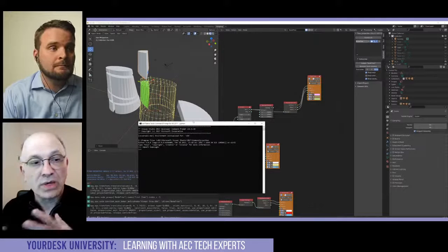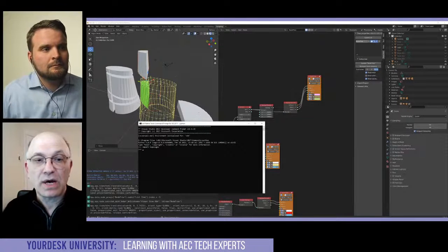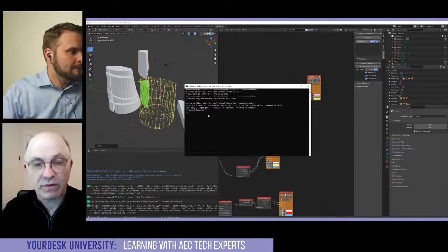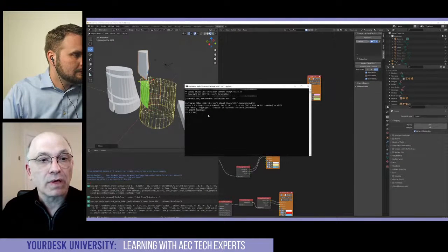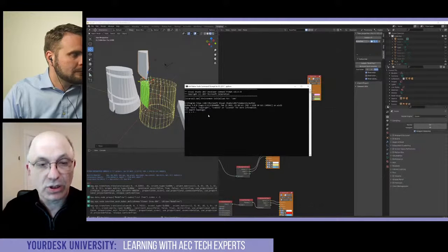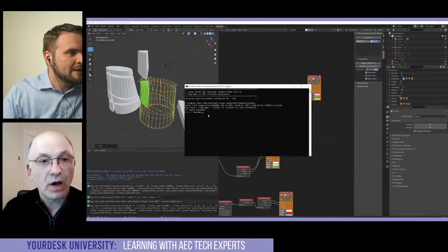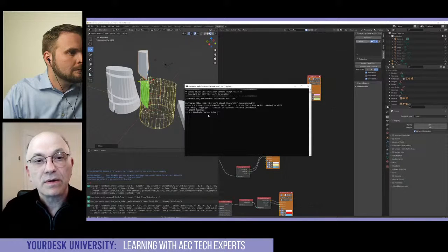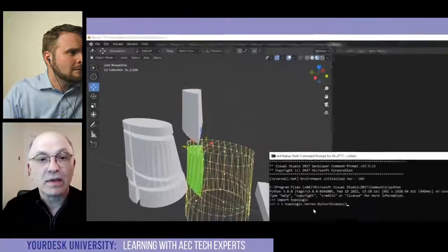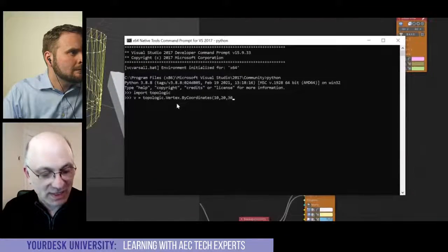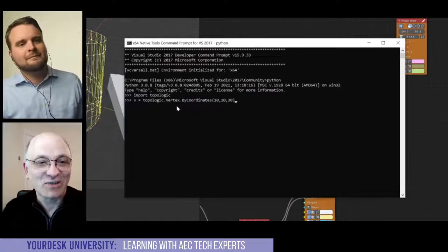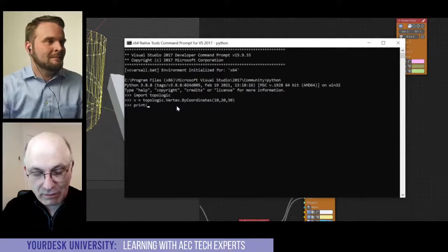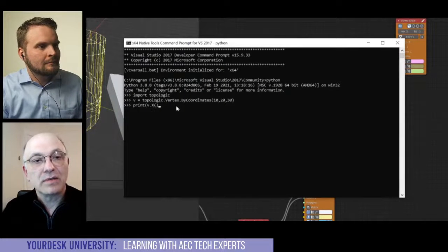In Python there is no visualization. Right now you saw I loaded it into a Python console, so I can say v equals topologic. Sorry, I have to do topologic dot Vertex dot by coordinates. Sorry, it's going to be a lot of typing, obviously. 10, 20, 30. As Theo always says, I like 10, 20, 30. So if I say print v dot the x coordinate, that's 10.